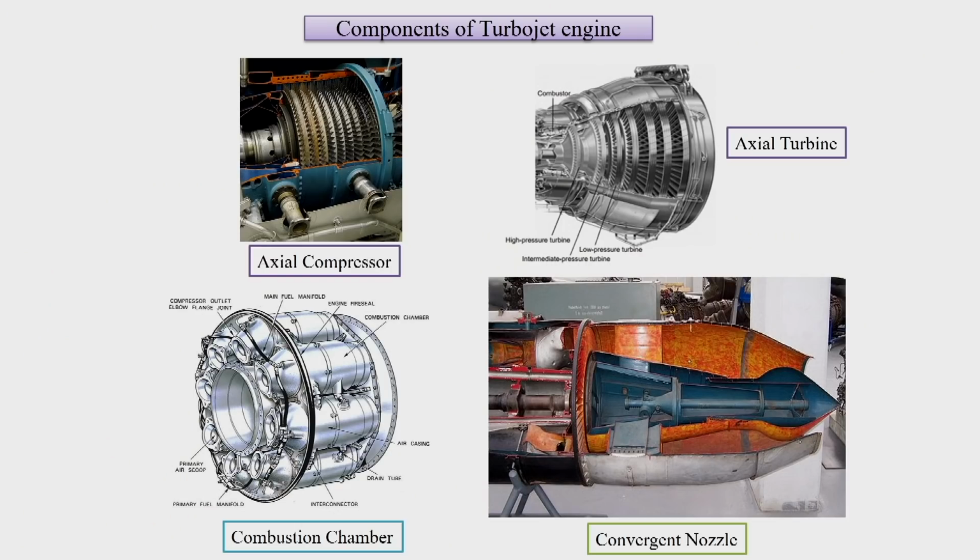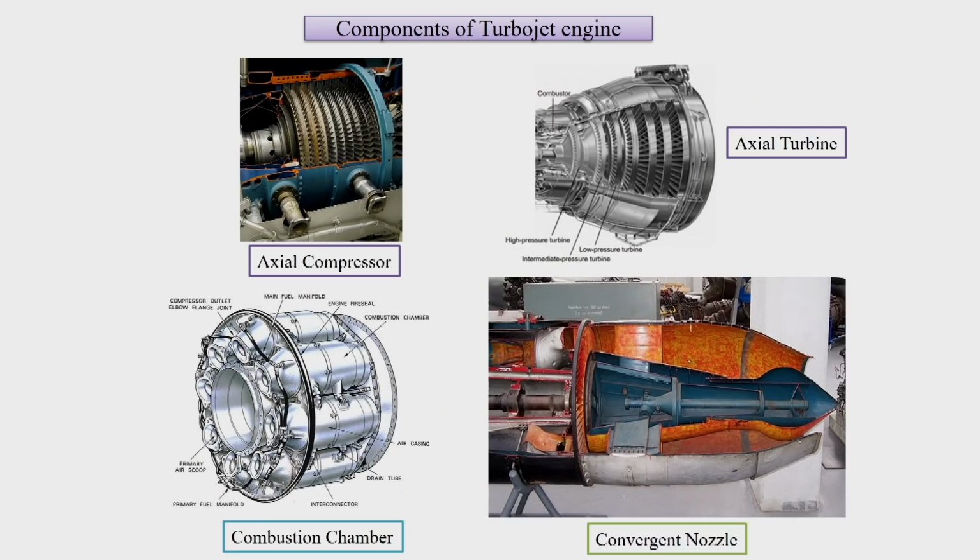Due to the pressure difference between the inlet and outlet of the nozzle, we would have an expansion, and in that expansion pressure decreases, temperature also decreases, and velocity increases. This increment in velocity increases the Mach number in the axial direction of the nozzle. The limit we can get at the exit is Mach number 1, which is called sonic.